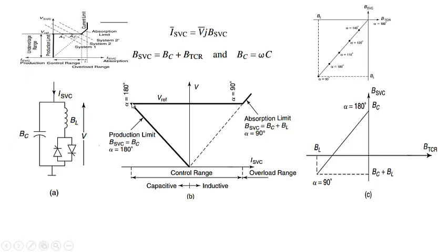Now at this point, if the system voltage increases further and we do not issue any firing to this, you'll see voltage will go on increasing, current will increase. In that case, as I have shown you, if the voltage increases, we'll issue a firing pulse to this as per the desired value. So the voltage will come from this point to this point, and A1 will be the operating point.